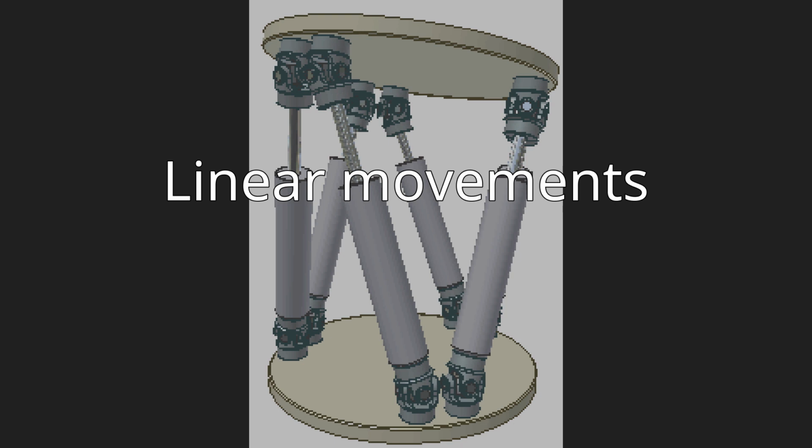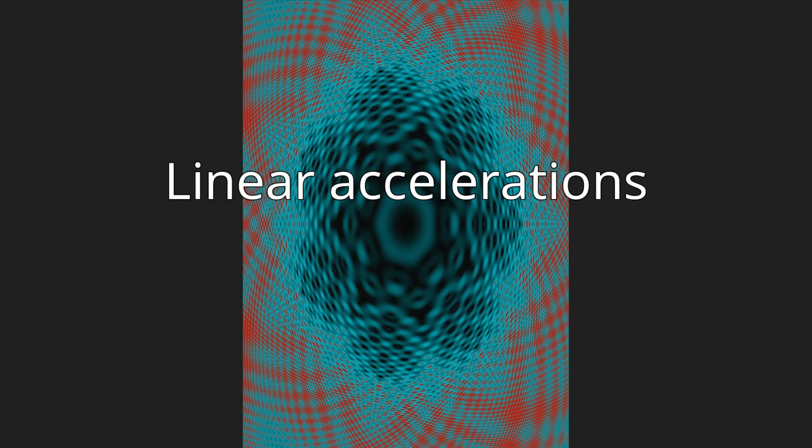For the case of constant linear acceleration, a substitute for the real situation is simple. Since the amplitude of the acceleration is not very well perceived by humans, one can tilt the subject backwards and use the gravity vector as a replacement for the correct resulting force from gravity and forward acceleration. In this case, leaning a simulator backwards and rotating the visual picture by the same angle gives the subject a force on the back. Linear accelerations, durations.